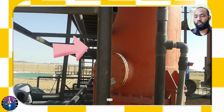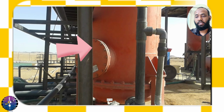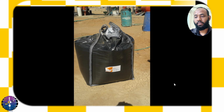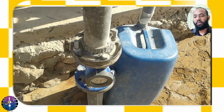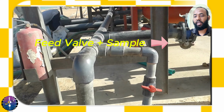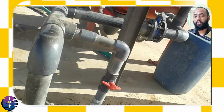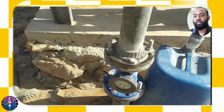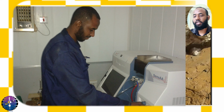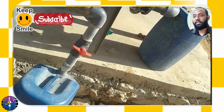These are the absorption columns designated for placing activated carbon. This carbon is made of a special porous material capable of absorbing the gold from the solution. We fill the column with carbon through an opening at the top. There is a valve called the feed valve, where we take samples from the solution entering the columns and measure the gold concentration using the atomic absorption device.